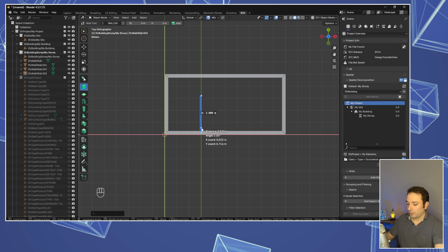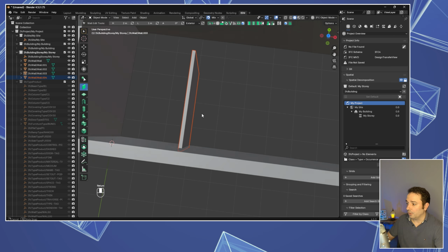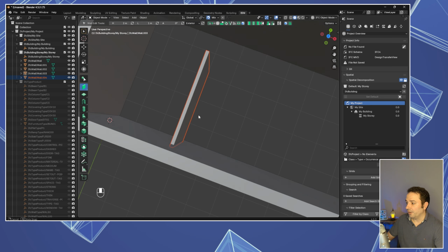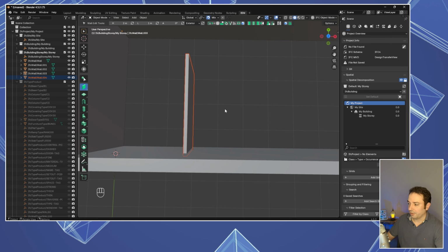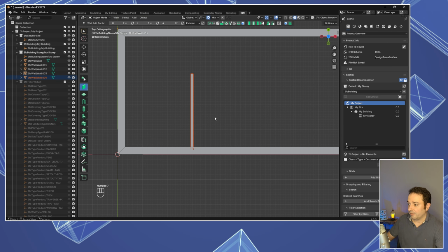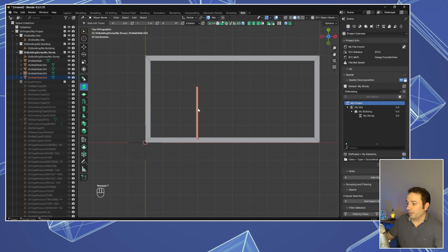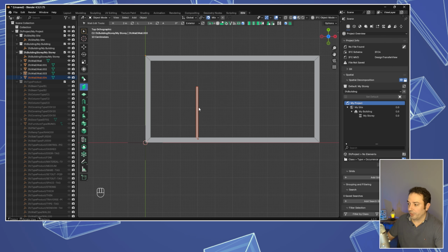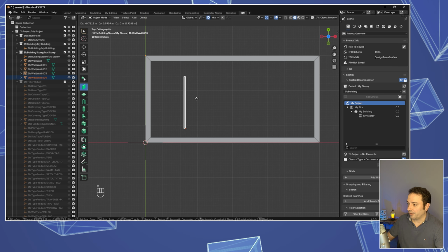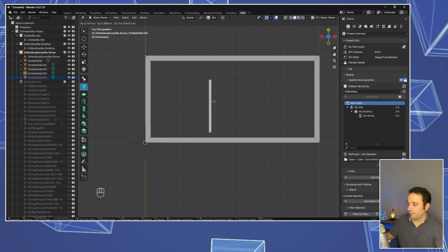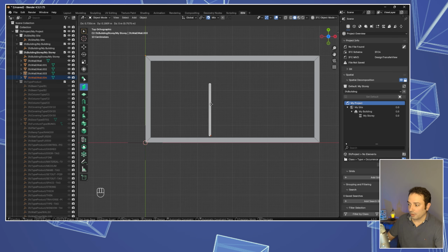The first thing I'm going to do is press Enter to create the wall. You can see the wall is in the random location that I was mentioning before. Let's press 7. The way to do it is by grabbing the object. We just need to press G, and you can see that now we have the possibility to shift this BIM wall wherever we want.